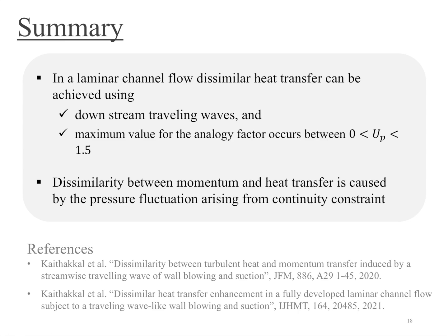Coming to the summary of the present study, what we have shown here is that in a laminar channel flow, dissimilar heat transfer enhancement can be achieved using downstream traveling waves, and the maximum value for the analogy factor occurs between U_p equal to 0 and 1.5. And dissimilarity between momentum and heat transfer is caused by the pressure fluctuation arising from the continuity constraint.